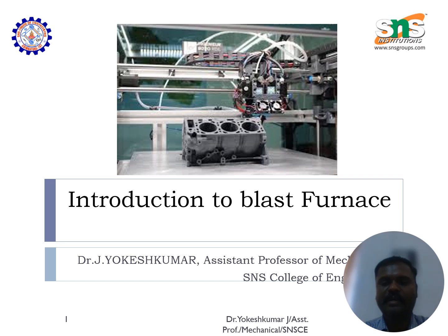For that we need to supply heat. The metal is subjected to metallurgical changes, which means it absorbs the heat, and microstructural and molecular changes occur in the metal, which converts the solid metal into a liquid form. Then finally the liquid metal is poured into a mold cavity. Upon solidification, it again rejects the heat and finally forms a solid. That solid metal is called a casting.